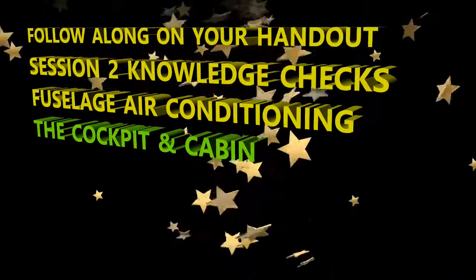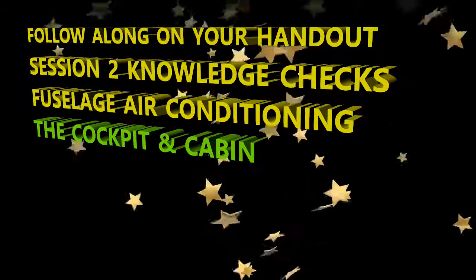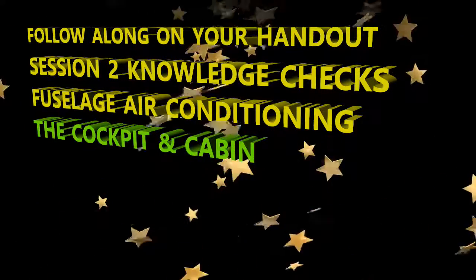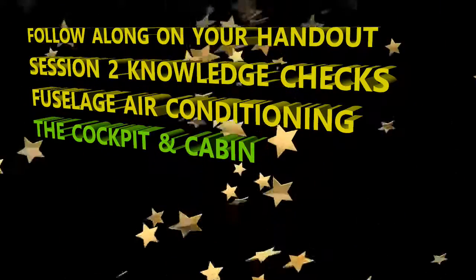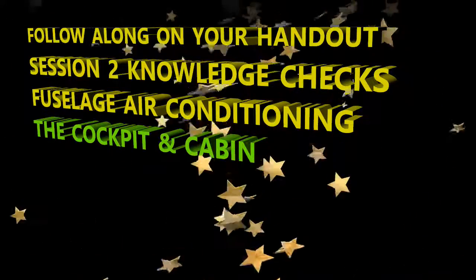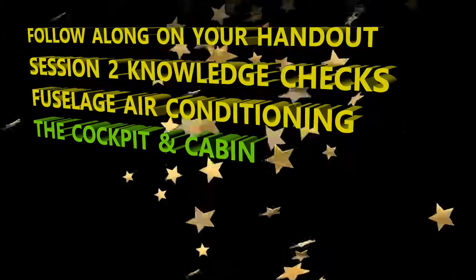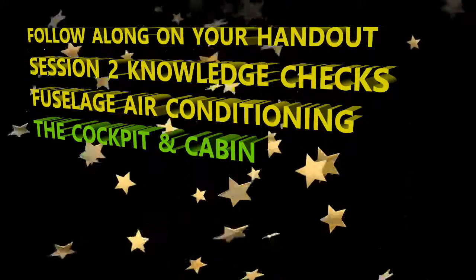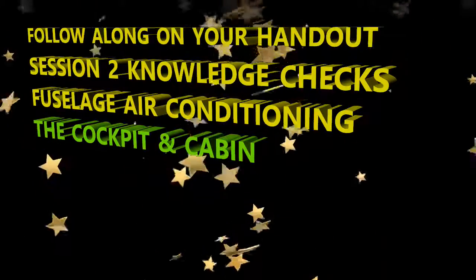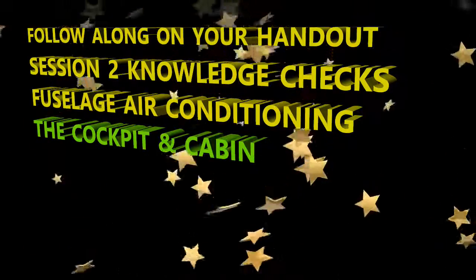Next question. When the pack controllers are in charge, it limits the water extractor outlet temperature to what temperature? Just take notes on this one. I probably didn't mention it, but choice A is 20 degrees Celsius for pack 1 and 10 degrees Celsius for pack 2. Choice B is 30 degrees Celsius for pack 1 and 40 degrees Celsius for pack 2. Let me say the question again. When the pack controllers are in charge, it limits the water extractor outlet temperature to what temperature? The answer is actually the first one: 20 degrees Celsius for pack 1, and it limits the outlet temperature for pack 2 to 10 degrees Celsius.